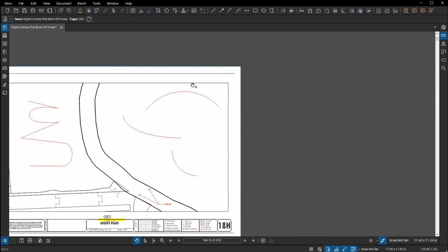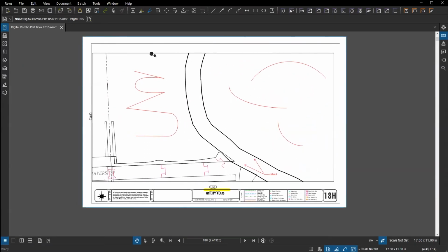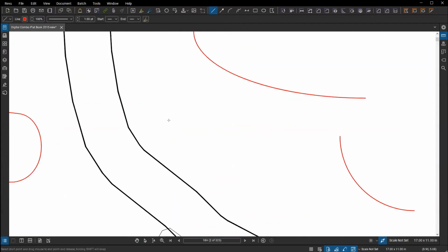Just reading through a couple of the questions that are here. As far as repeating, so as far as you wanting to keep on selecting the line button, it depends on what you have turned on for what's called the reuse function. So if you have reuse enabled, you'll stay in the tool until you tell the software that you're done. One of the common examples for that is line. So if I just hit L for line, without reuse, you start it somewhere, you stop it, and you're out. The command is satisfied. You have both points defined for the line, and you're finished. To reissue it, you pick line again.